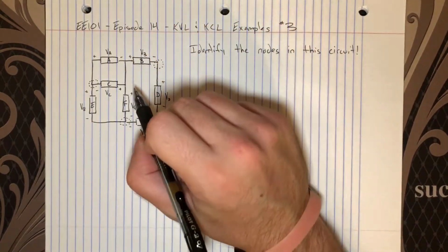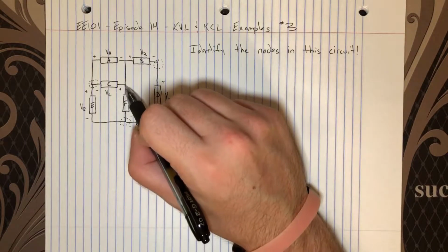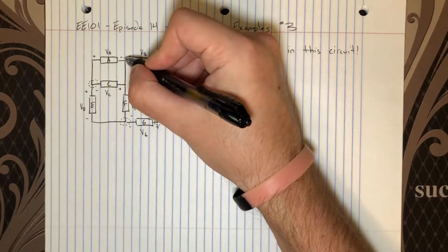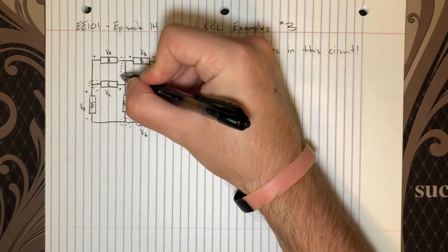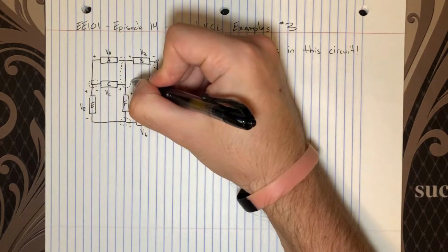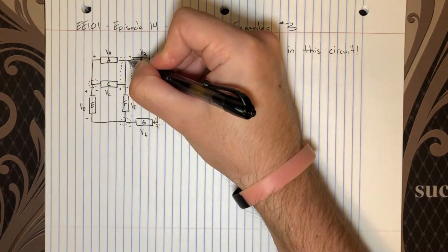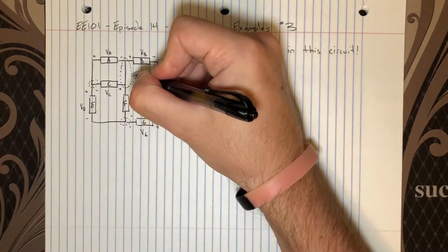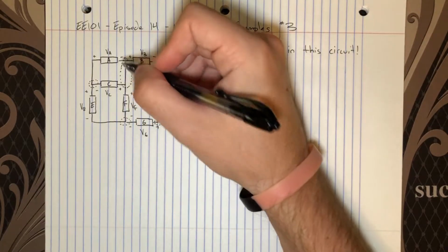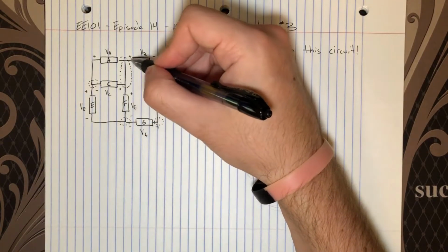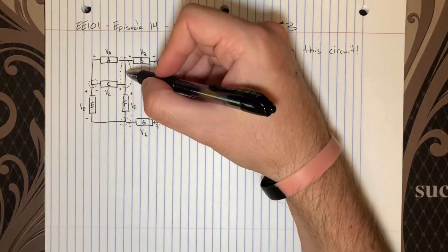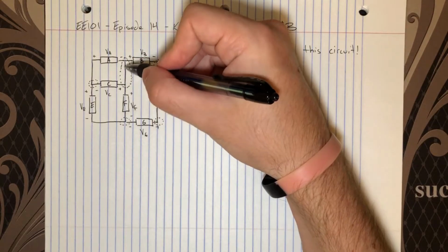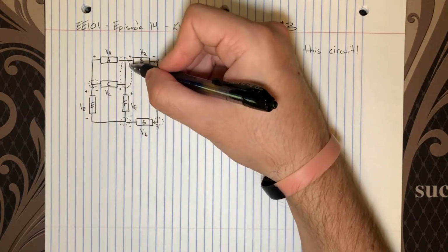And you might be tempted to say, oh look, C and F make a node here and A and B make a node here. But really, no, all 4 make a single node because they're all connected together by this same patch or intersection of ideal conductors. So this whole area that I'm circling here is really just a node. This is a short circuit between all these elements, and therefore this entire network of wires that connects these 4 elements would have the same voltage.